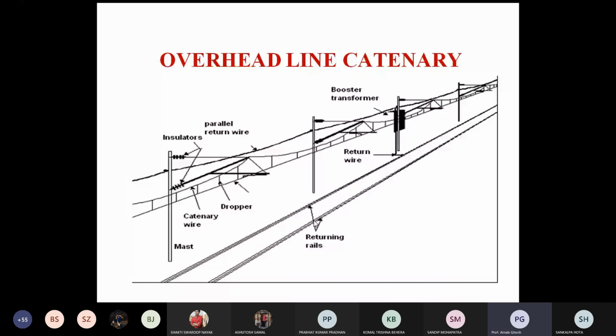Then delta to delta transmission, throughout the transmission, all the time you are using delta configuration. That delta is coming from the transmission substation to the distribution substation, and again from the distribution substation to your locality's pole mounted substation. Then again you are converting the delta to star configuration by using a DY11 substation. That is distribution. The rating of your pole mounted substation is normally 100